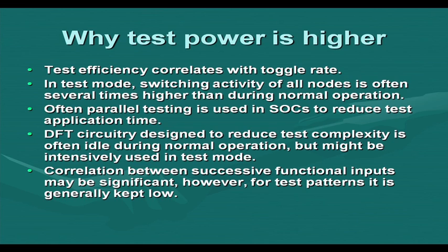So that becomes a positive feedback on the system, which will be catastrophic. That may cause a thermal runaway. We will come to those issues later, but in testing mode, power consumption minimization becomes an important issue.